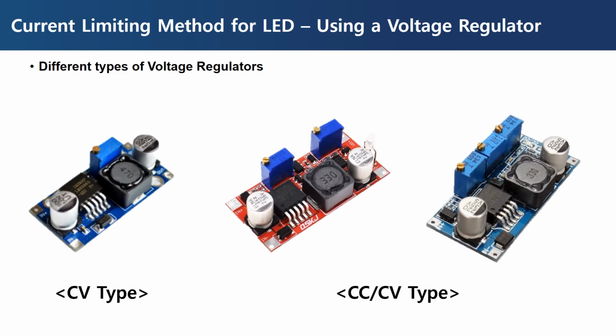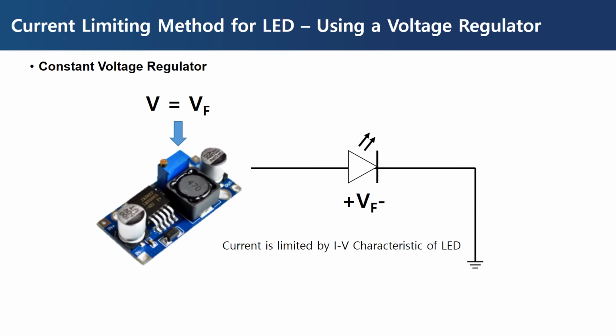LM2596 doesn't inherently support constant current, but it supports constant current through the extra circuit added to the module. If you would like to learn more about the operating principle of this module, please refer to the video related to LM2596 in my video. Let's review the case of using a constant voltage-supported regulator.